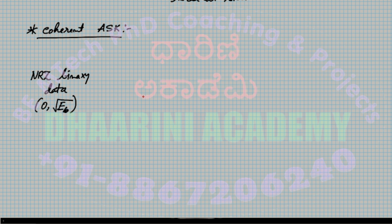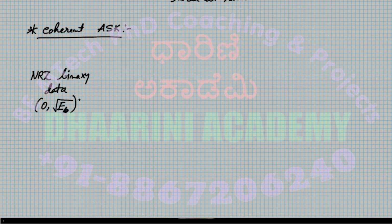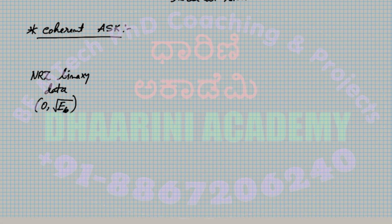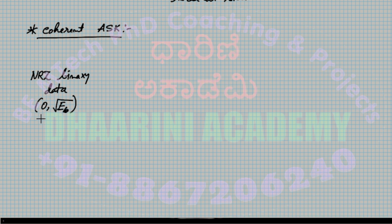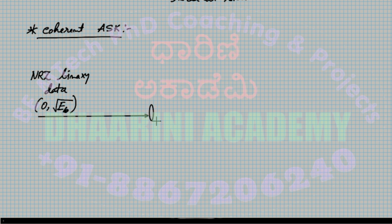And this data is passed through a multiplier circuit. But when it comes to communication, the multiplier circuit is called a product modulator. That's a technical term, right? So we denote the product modulator by writing an X symbol over there. It's a multiplier, basically, we can understand that it's going to multiply two different signals.